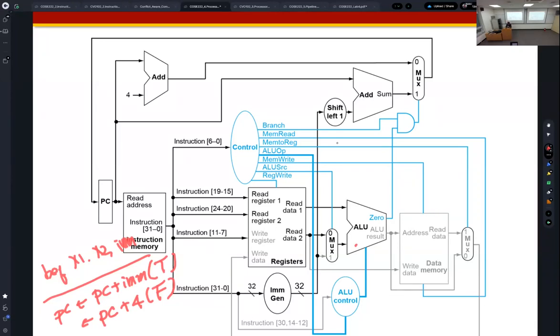So MemToReg is don't care here, because the branch instruction just updates the PC. RegWrite is also 0. How about the ALU source? The branch instruction uses read data 1 and read data 2, RS1 out and RS2 out, which means the input operands come from the register file.